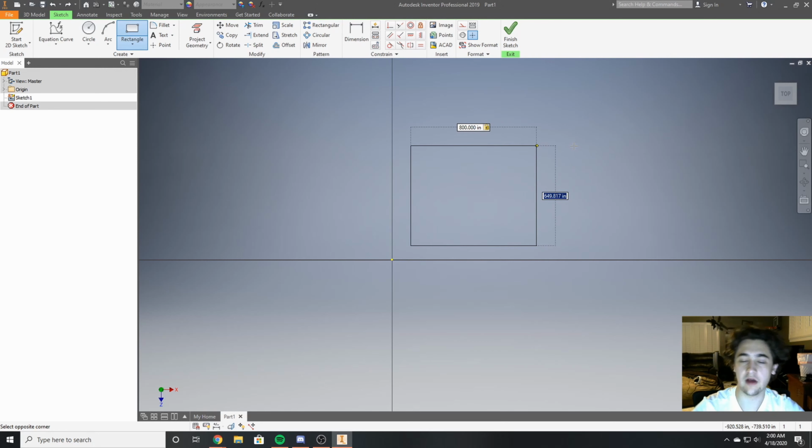Click the tab key. That one's set now. I can't change this length. I can only change the height now. Say I want this one to be 300. Click tab. This is all set. I can't move it unless I go in here and change that to 400. And the way I'm switching between these is by clicking tab again. Whenever I get this set right, I click enter, and then boom, I got my thing. That was a 2-point rectangle.